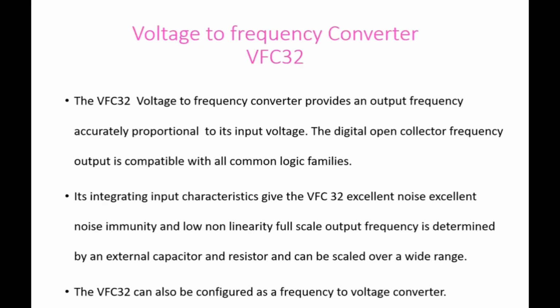Here I am using VFC 32. It is a voltage to frequency converter, providing an output frequency accurately proportional to its input voltage. The digital open collector frequency output is compatible with all common logic families. Its integrating input characteristics give the VFC 32 excellent noise immunity